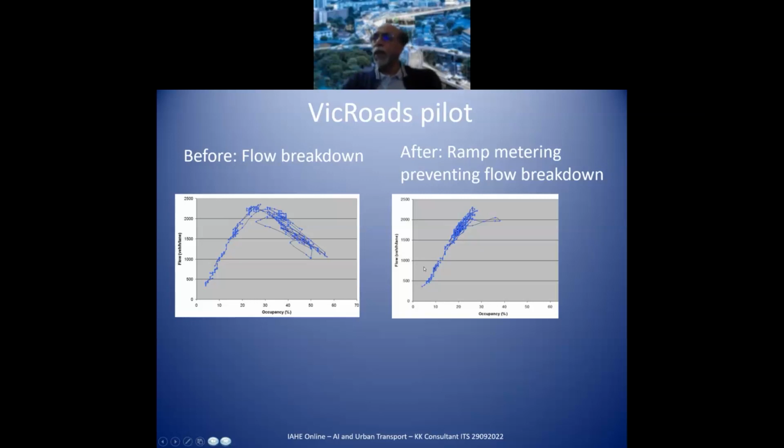You know what is a ramp meter? In India, we hardly use it, but we often understand, when there is a flyover to be climbed up, in Delhi, if you are just coming out of the airport and want to get onto the first flyover, you can find a big jam because there is no ramp meter there. And similarly, at the point of joining highways from the side roads, you will find again a jam there. These jams are managed by ramp meters. Ramp meters are signals that keep the traffic joining smoothly with each other. The merging is made smooth. By introduction of the ramp meter, it is similar to making the rice particles go directly through the funnel.